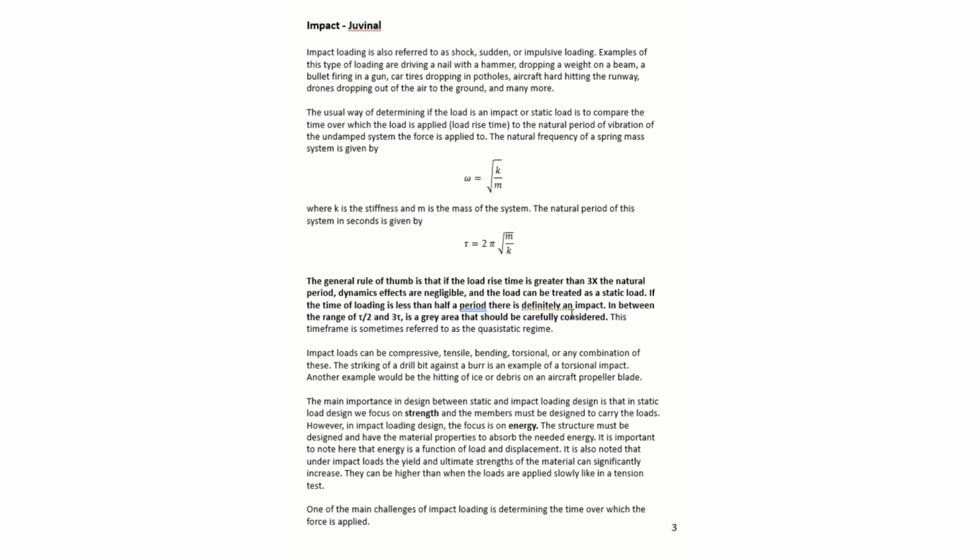Some of the bad things about impact loads is they can be very destructive and they can be very large. We also know that impact loads can be tensile loads, they can be compressive loads, we can have bending stresses, torsional, and any combination of these loading types can be due to an impact.